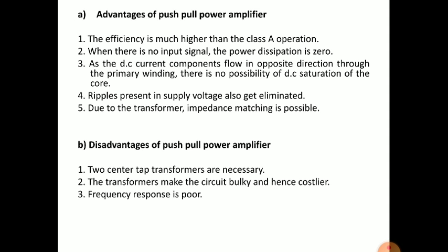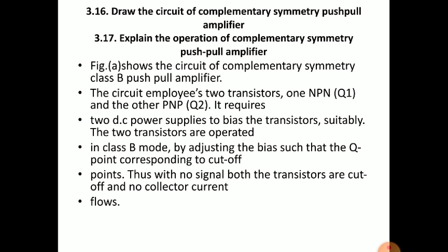Ripples present in supply voltage also get eliminated. Due to the transformer, impedance matching is also possible. Disadvantage: two center tap transformers are necessary. Transformers make the circuit bulky and hence costlier. Frequency response is poor.